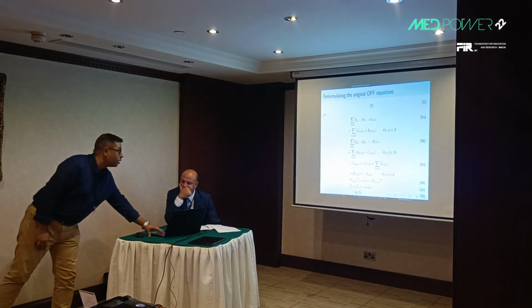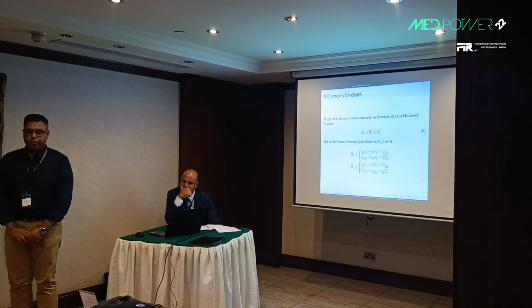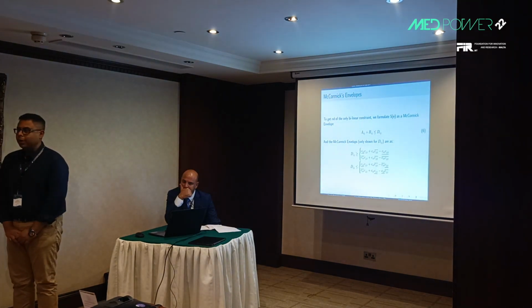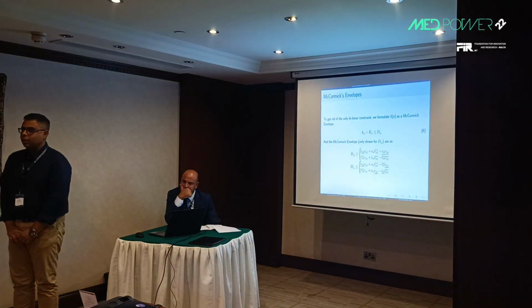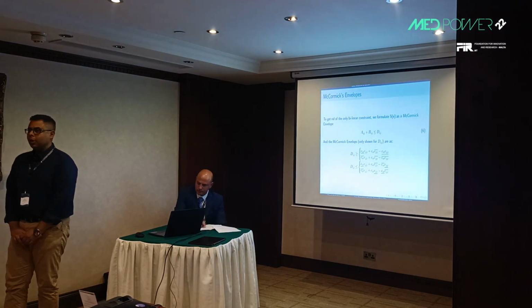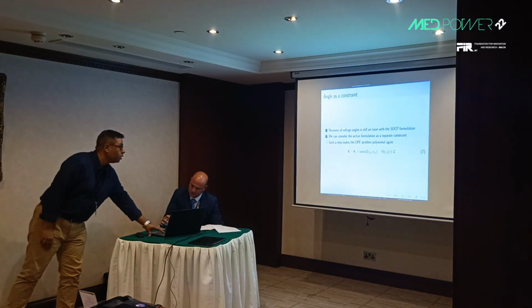But to have the equation of the circle linearized, we further use McCormick envelopes to make the equations fully linear. This way we achieve a better relaxed solution without compromising the computational accuracy and the speed of the OPF solution.